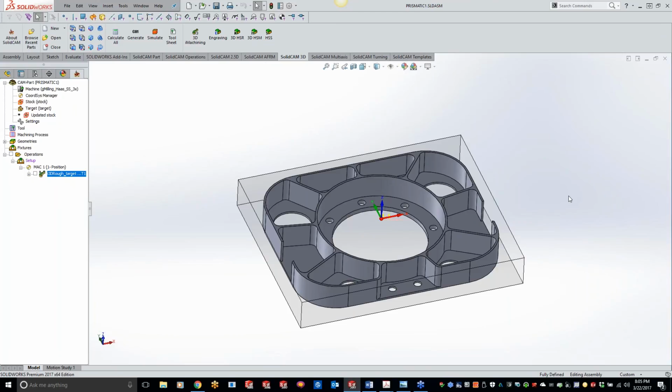We're utilizing a 3D toolpath and able to throw it onto a 2D part, but very easily. And that's the key point right there. So with Prismatic, it combines the constant Z and 3D constant step over together. What it does is look at the entire part, and we're going to be able to finish our straight up and down walls and our floors all in one toolpath.